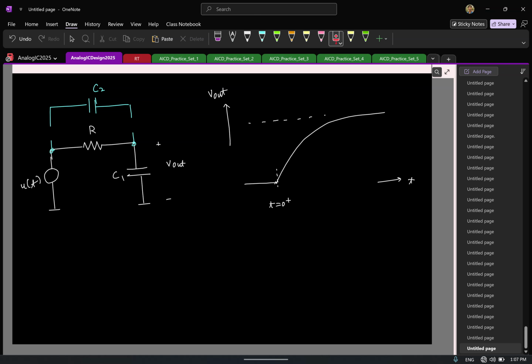Nothing about the resistor being shorted. Let us say impulse current flows here, for example. What can you say about the voltage drop across the resistor? Impulsive. But you see that neither of the voltages are impulsive. So, by contradiction, we can say there cannot be impulsive currents flowing.